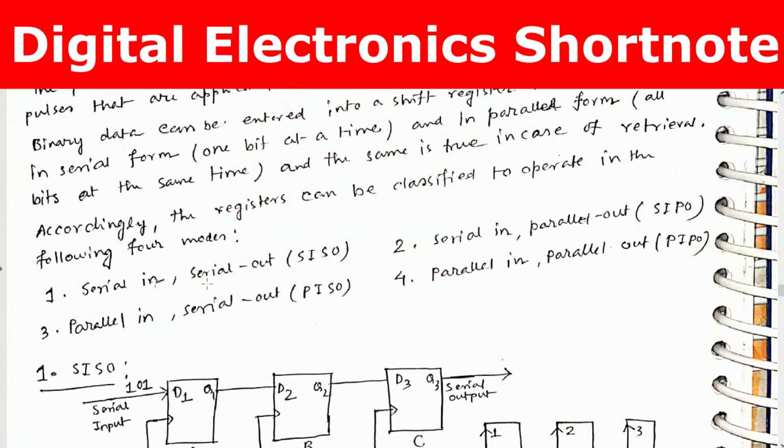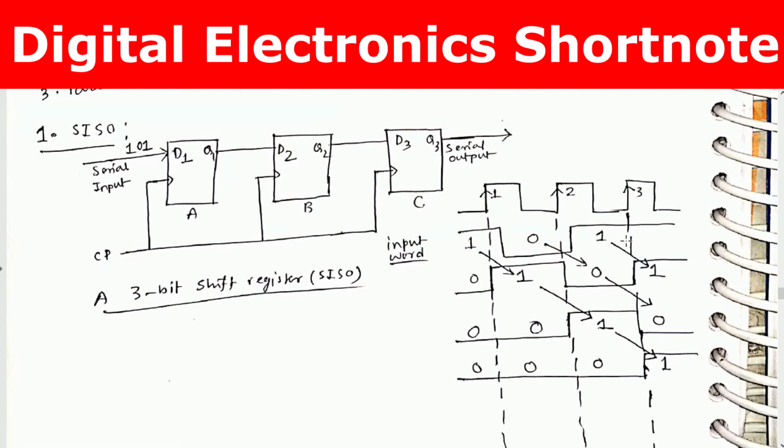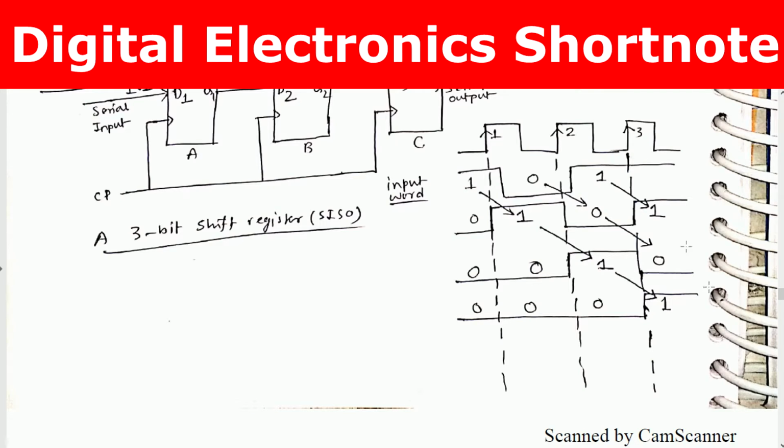Accordingly, registers can be classified to operate in the following four modes: SISO, PISO, SIPO, PIPO. That is, serial in serial out, and in the same way parallel in parallel out, serial in parallel out, parallel in serial out. So this is the configuration of SISO, serial in, serial out. Data is entered serially and data is taken out serially, that's why serial in and serial out. This is a 3-bit SISO shift register, and it works in this way.